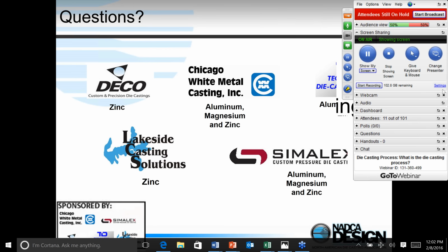The die cost doesn't really depend upon the number of units being produced. Generally, the dies are all produced in the same way. You would generally produce them all from the same kind of steel. The steel is a minor part of the production costing of a tool. It's the design work and the fabrication that is where most of the cost comes from. Maybe for that low production, you could produce it from a hardened steel tool, which might take 10% off the cost or something like that. But you really ought to go talk to a die caster.